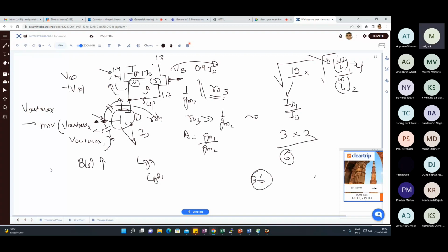That is different, that depends on the application, right? So if your signal itself is high frequency, what will you do? You need to cater to the signal bandwidth. So whatever the signal bandwidth is, you need to meet that. Then comes the noise consideration. You can't say that because of the noise consideration, I will limit the bandwidth. Bandwidth is decided first by the signal requirement. Then you can minimize after that.